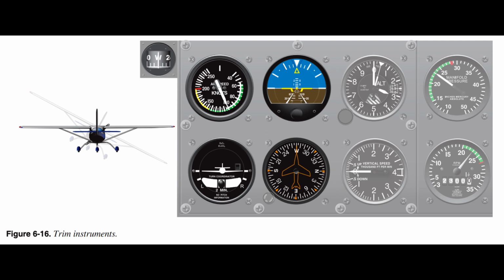The specific use of primary and supporting instruments during basic instrument maneuvers is presented in more detail in Chapter 7, Airplane Basic Flight Maneuvers. Fundamental skills. During attitude instrument training, two fundamental flight skills must be developed. They are instrument crosscheck and instrument interpretation, both resulting in positive aircraft control. Although these skills are learned separately and in deliberate sequence, a measure of proficiency in precision flying is the ability to integrate these skills into unified, smooth, positive control responses to maintain any prescribed flight path.